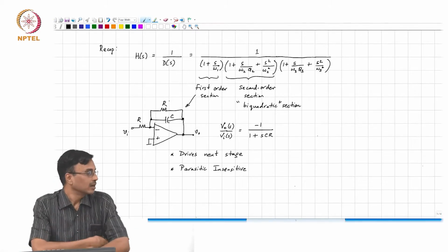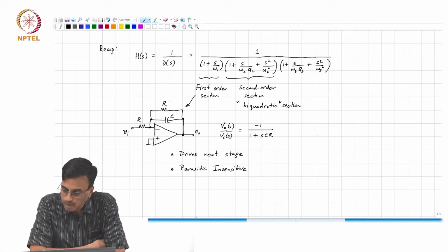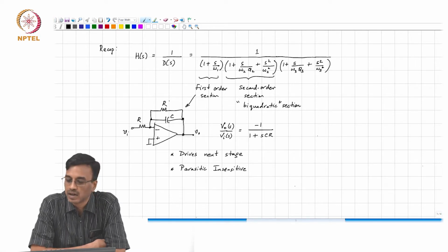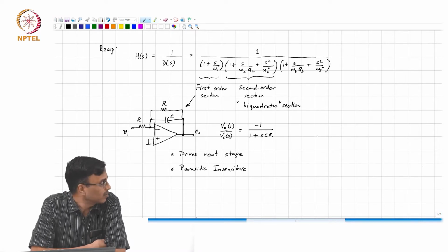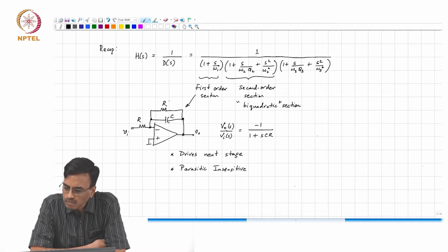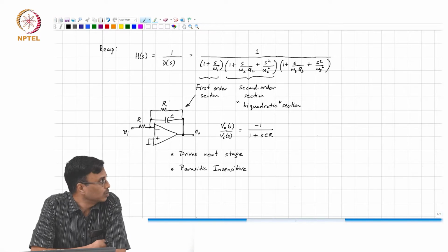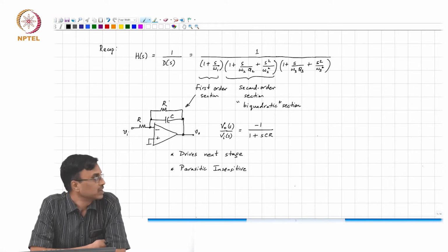In the last class, we were discussing the realization of a high order filter transfer function. This could be an arbitrary filter, but so far we've looked at all pole filters, and we've approximated the ideal brick wall by using the Butterworth polynomial. We then realized that we can break up a high order polynomial into a product of first and second order